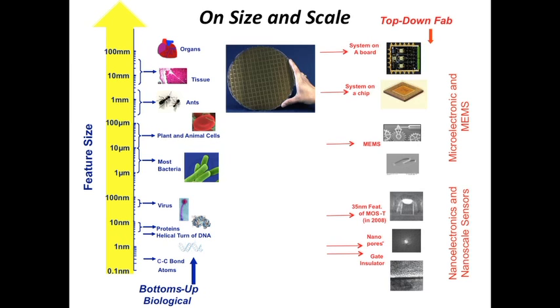Let's say now your pore is 10 micrometers and there is a cell of 8 micrometers. Now if the cell passes through it, it will physically block about 80% of the pore, right? And then you should be seeing less current during that time. If this is your current, let's say 1 ampere, when the cell passes through it, the pore will be physically blocked for a very small fraction of time. So you will see a dip in current, and then once it's done and it's on the other side, the current will come back to the normal state. In that way, you will get pulses as the current is passing through it.